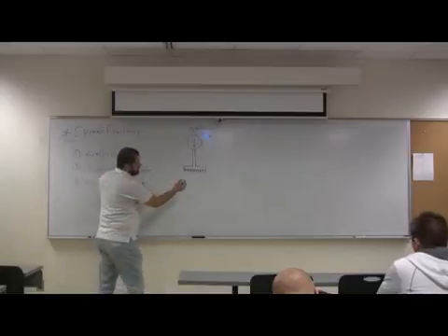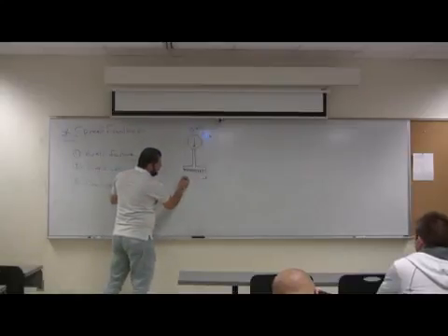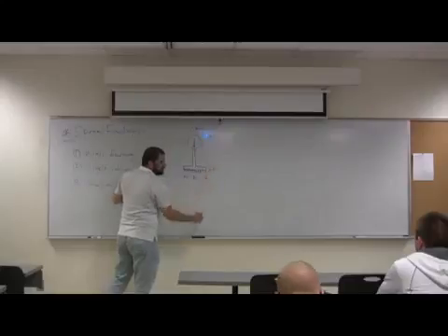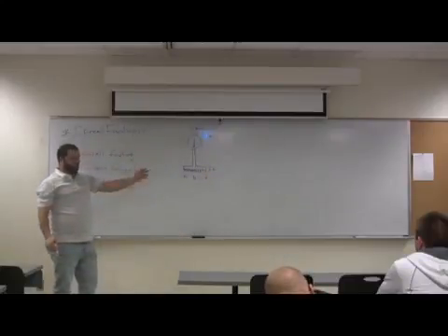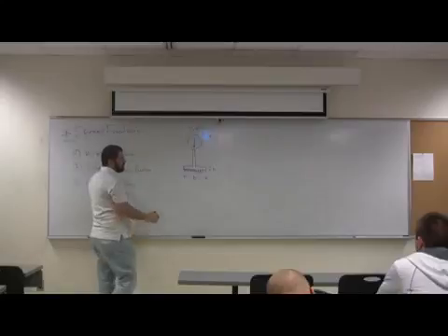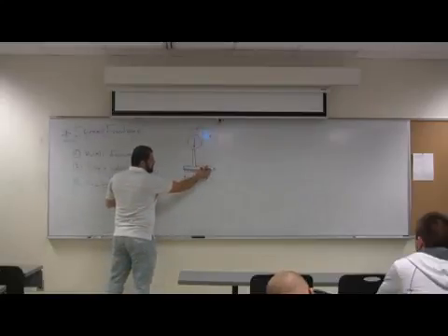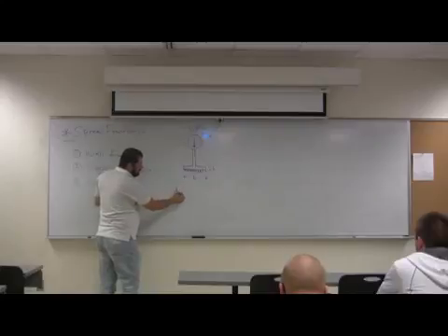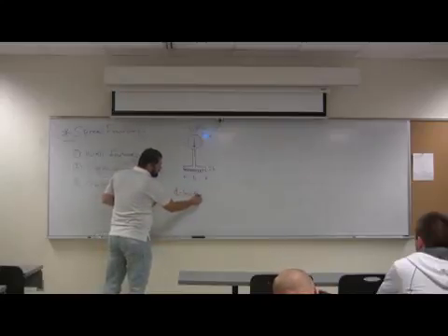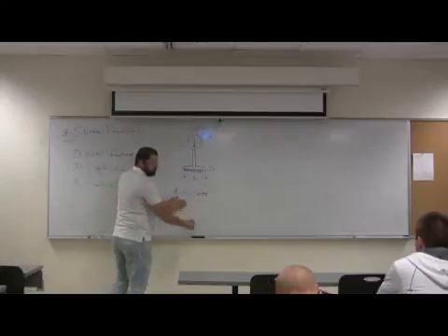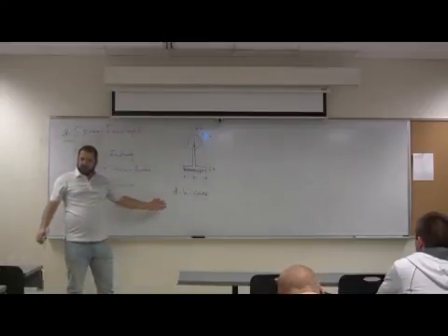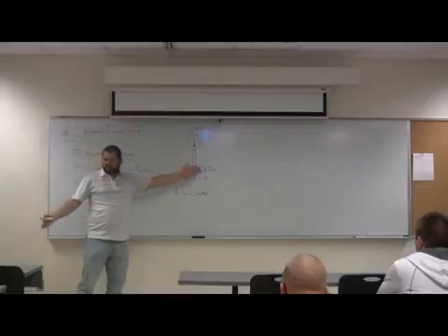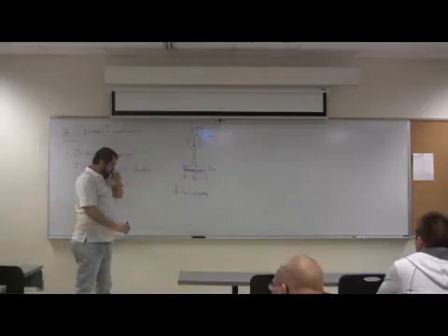Okay? So in our design, what we are required to do is to calculate the required B, the width, and the required H. B and H. Okay? That's what we need to come up with. And from H, we know d equals H minus the cover, because we use d in our strength calculation, in our flexural design. Same as beam design.